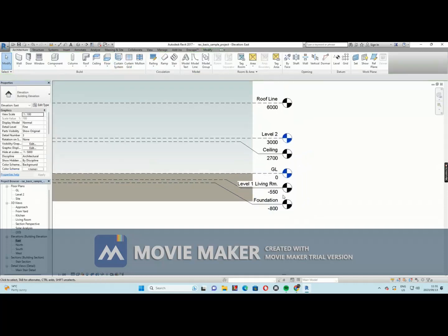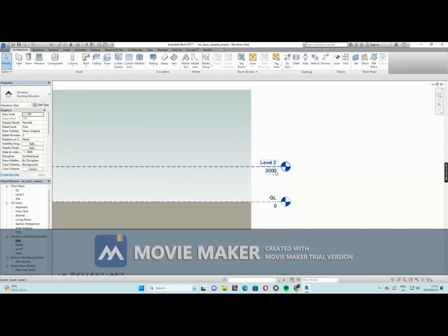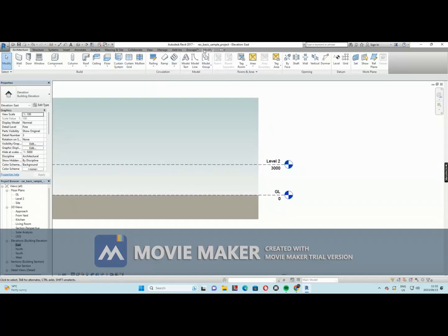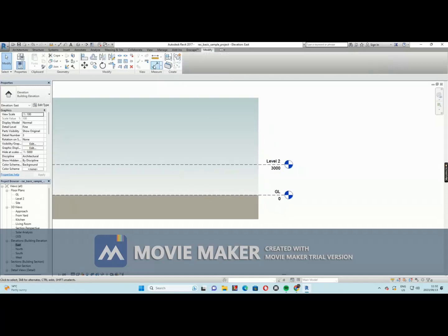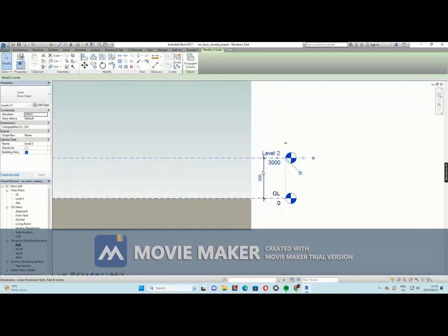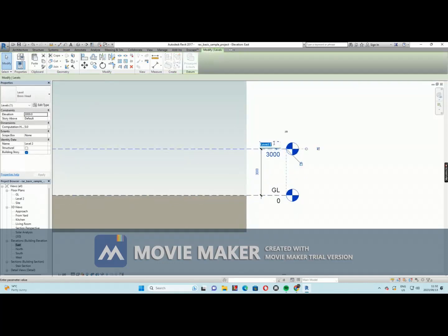We only have level 1 and level 2 on our project. I renamed this one to ground. Let me name this one maybe to my ground 3 meter. Let me take this one to 3 meters. Fine. 3 meters fine. Let me call this one top of first floor. Top first floor. I want to do a double story. Let me get another level.